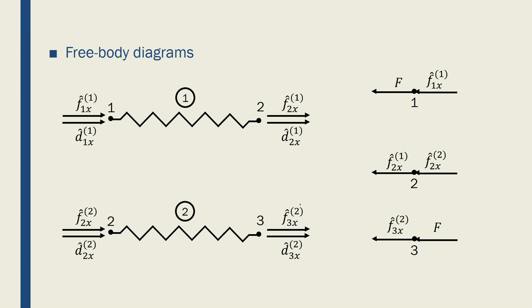And remember, that's because they're right now attached to element 2. And we have F2x2 and D2x2, which is different from here and here. So the second node, displacement and force in the x direction when attached to element 2, and the second node, force and displacement in x direction when attached to element 1, all in the local coordinate system.